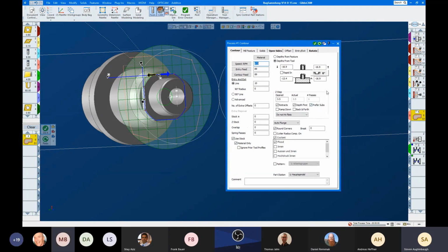Okay, Daniel, yeah. We saw in the early days some strange behavior in pocketing, etc., when round corners wasn't checked because customers kept feeling that they need to eliminate some moves, so they kept on checking that box. Yep. And then suddenly we ended up with a pocketing that didn't clean out the pocket and situations like that in the early years. So it seemed to me, and you can of course comment and correct me, that the pocketing, etc., was designed to use round corners as a standard behavior. Everything was written like that. And the aftermath was creating that sharp edge toolpath, which created some new problems.